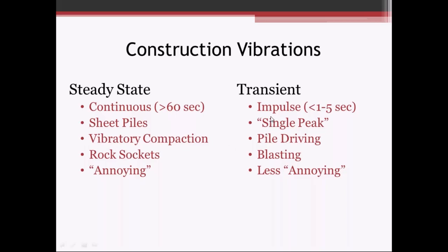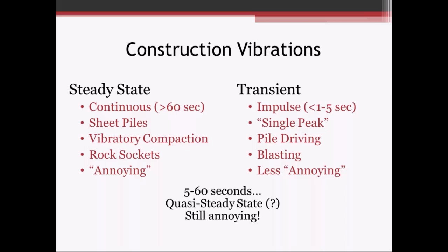These transient waves are sometimes a single event, like blasting. They've got a single peak. They last less than 5 seconds, usually on the order of 1 to 5 seconds. A little less annoying. But if anybody's ever been around pile driving, it's considered a transient event. Each one of those impacts is a transient event, but certainly plenty annoying if you've been around it long enough.